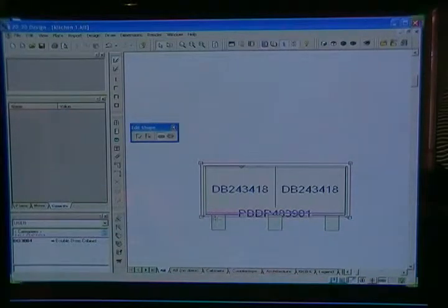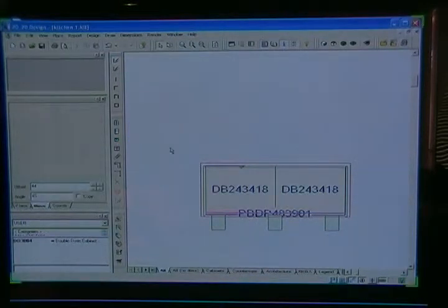Why? Because I'm going to have a raised top here. And notice I have corbels already placed onto my island. I'm going to select the check mark to OK it. And now I can actually draw a countertop that's going to go above my corbels as an eating area. And it will also be raised.